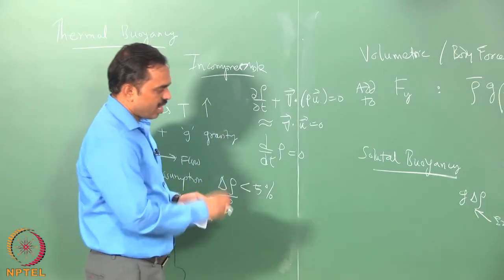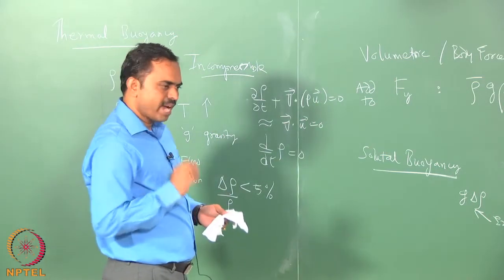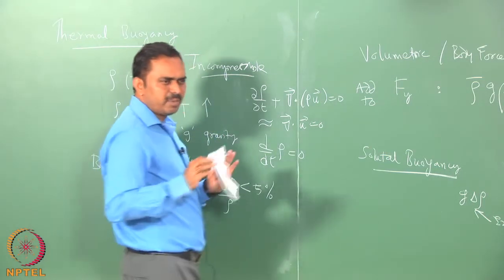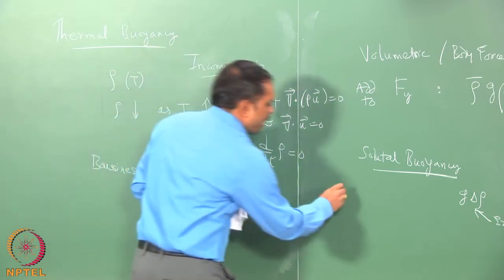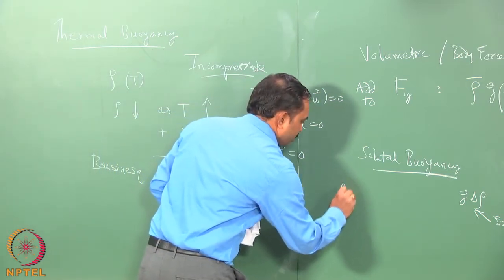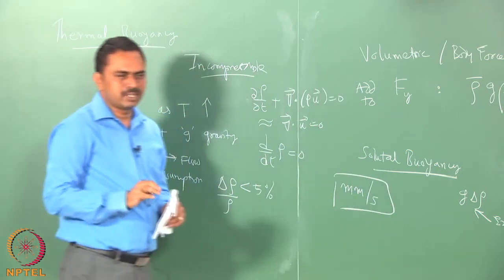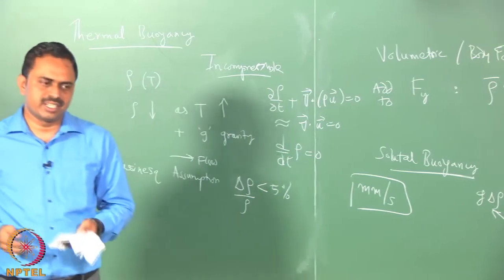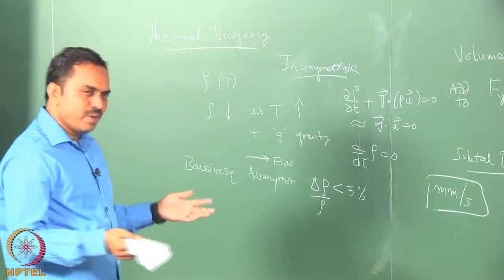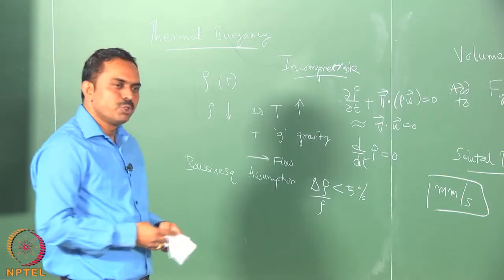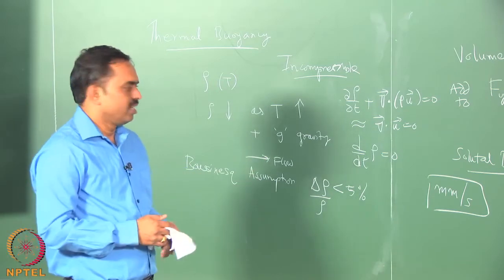And how would the average magnitude look like? It would be, for typical weld pool shapes, in the order of millimeters per second, which means that it is a very weak convection we are talking about. So, that is the reason why many of the models usually ignore the buoyancy term, because it is very weak.